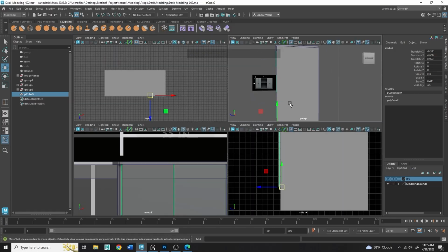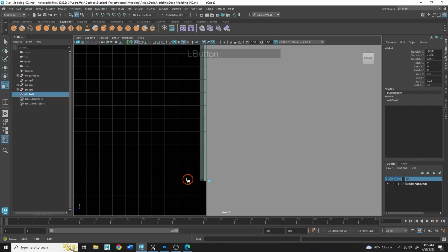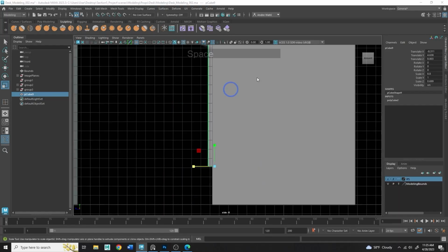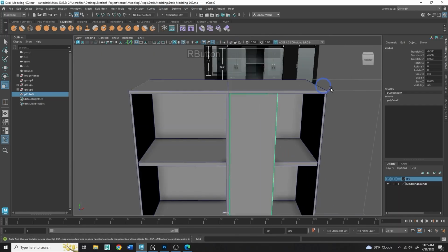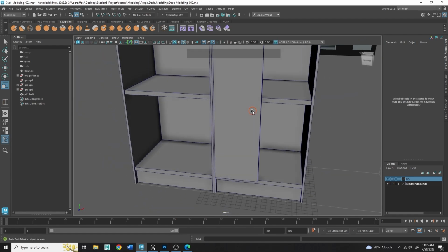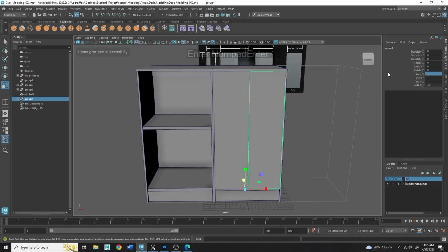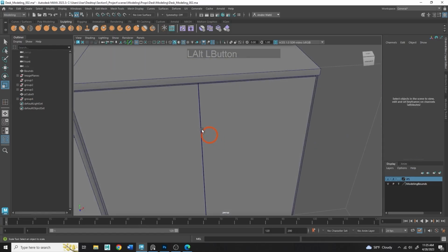In which case, since it wasn't sitting inside of there, I need to scale it again to be the correct size to match the concept. And these aren't going to open for our scene, but if you did want to open them in a future scene, you could. But that will get that set up there. I can then Control-D, Control-G to scale, move that -1 in X, and those doors should be aligned nicely.